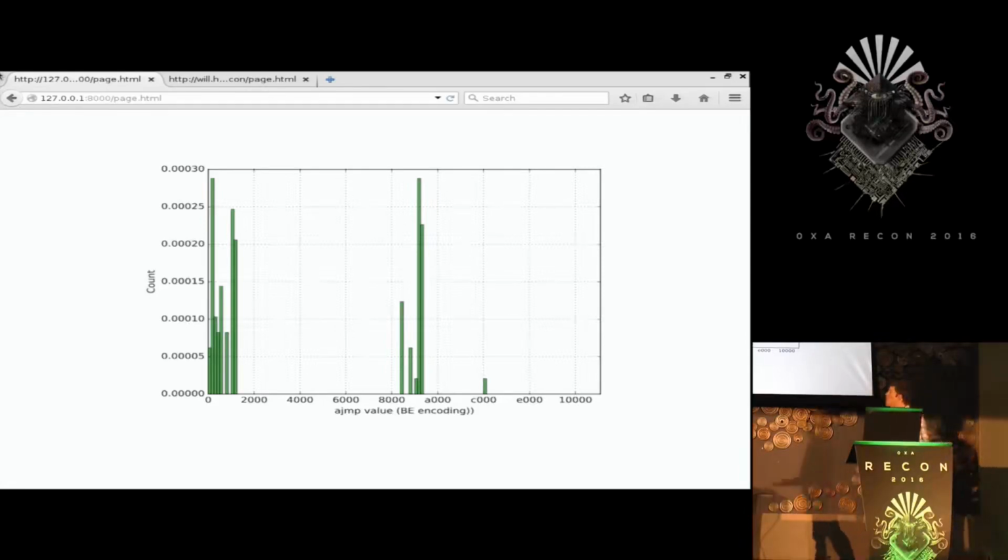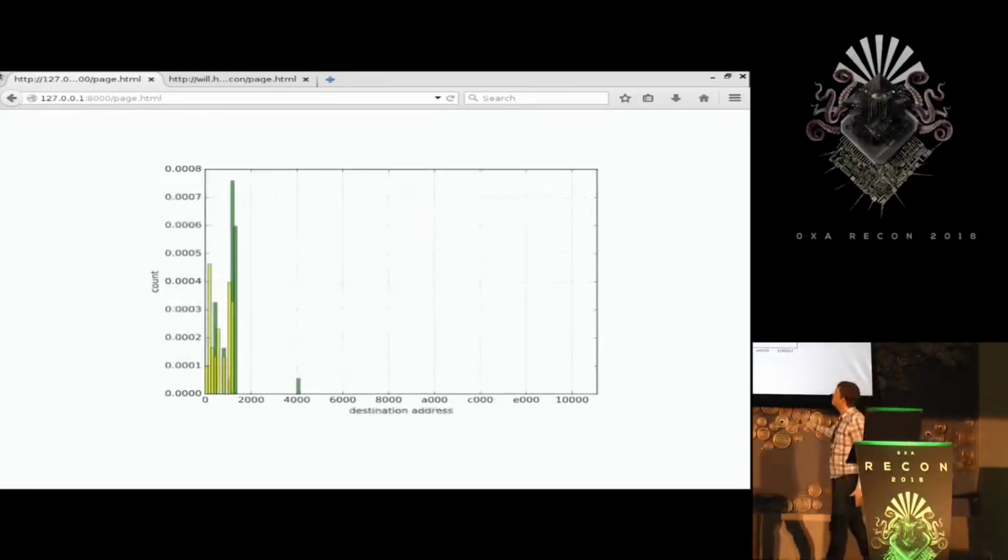What's probably more likely is that the 15th bit is actually a selection. It differentiates between 2 different instructions that both take an absolute address. And so the hypothesis is that the 15th bit is part of the encoding, not the address. And if we follow that hypothesis, we see something that looks much more reasonable.